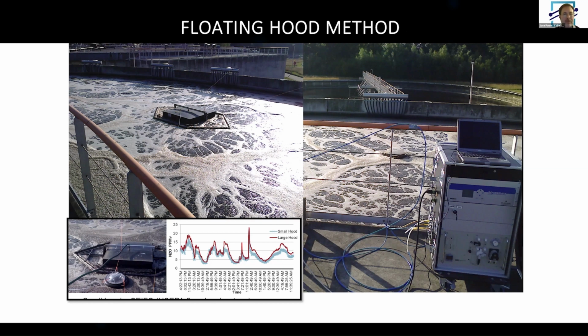But it also depends on the situation, because you could also have a non-aerated zone upstream from here where N2O can be produced, but it won't be emitted until it gets here. So if you do measure something in the off gas, you're not going to know how much is from the actual production here and how much is from the upstream anoxic zone.